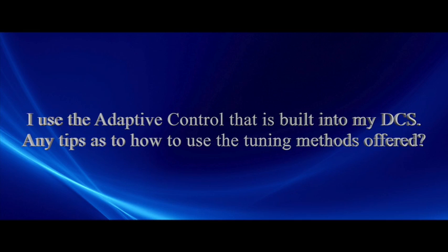So you have to go into the PID options and say, I want to set lambda, and I forgot exactly what the PID option is, but it's pretty obvious that lambda can be set not as a factor of a time constant, and for integrating processes, they try to make it a factor of the integrating process gain. If you can set lambda not as a factor, but as an absolute value, then you can choose in your mind, hey, I want to set it,